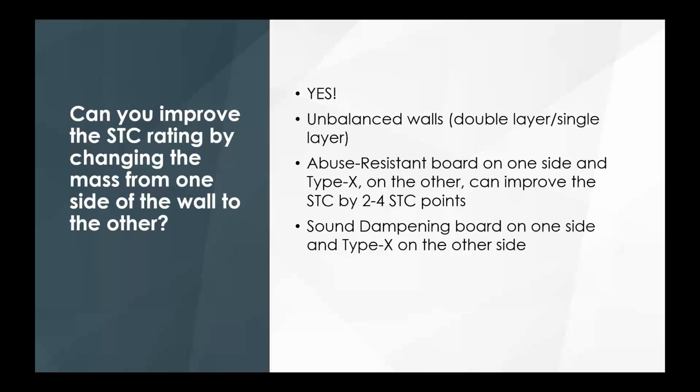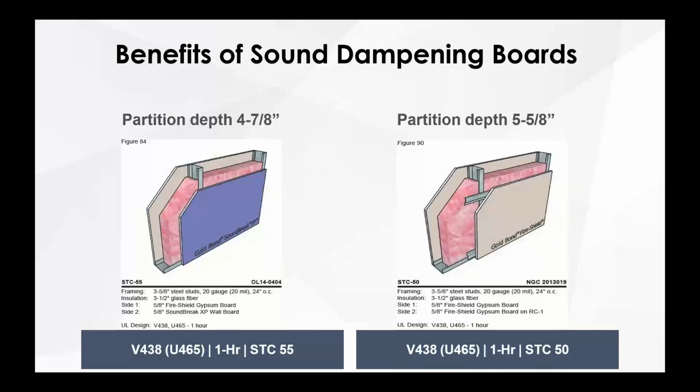Now, the way you're typically seeing this more times than not is with a sound dampening board. And that makes a huge difference. Sound dampening board on one side, Type-X on the other is going to make a big difference in the STC rating. Let's take a look at what that looks like.